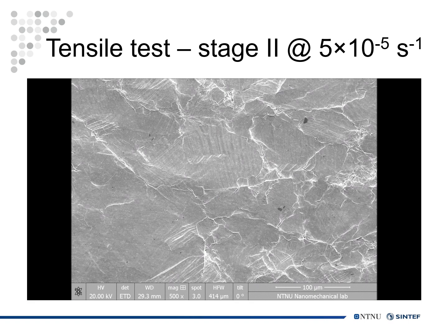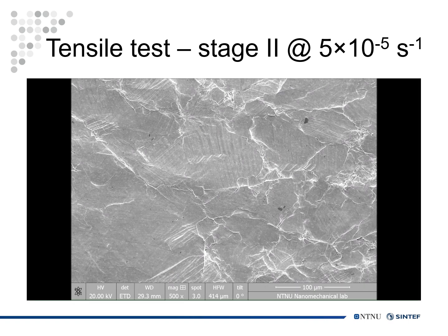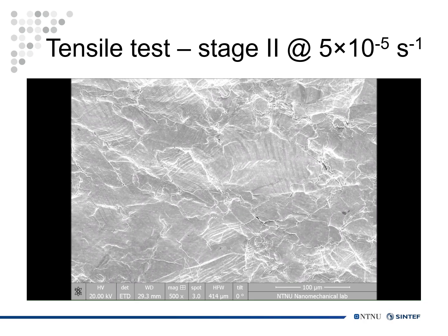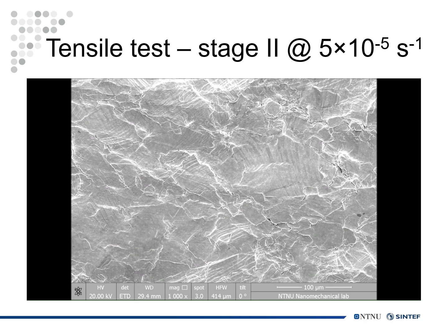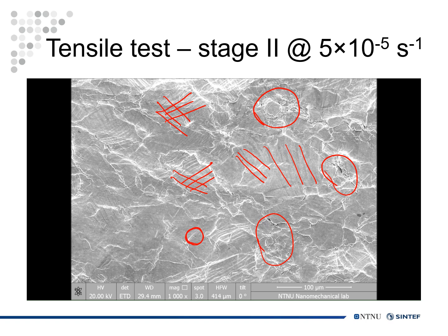The second stage involves higher strain levels. The deformation accumulates more at grain boundaries and the damage becomes more significant, such as this area, and this area. The slip lines occur in different directions, such as these ones, and these ones. There is also a slight debonding effect close to the precipitate faces, but not very significant.